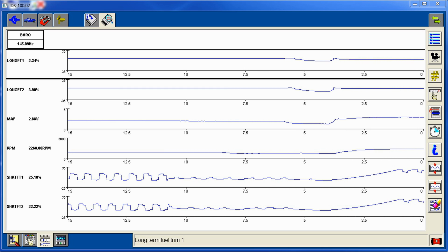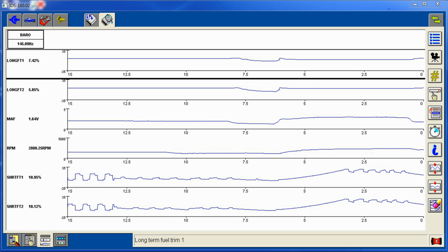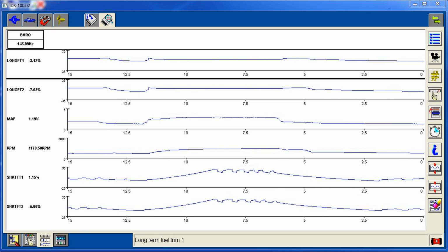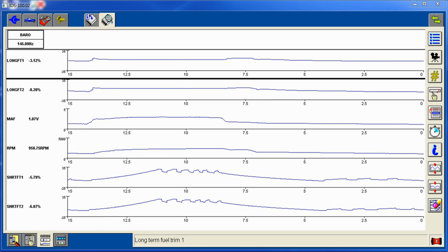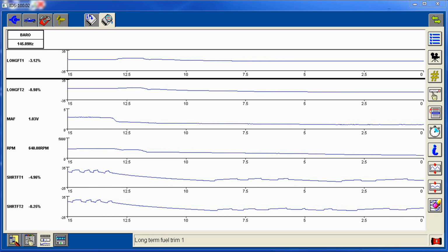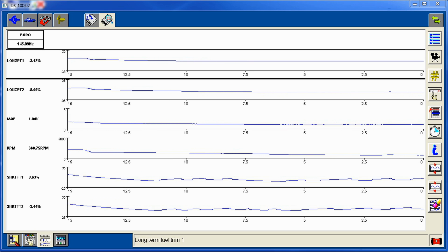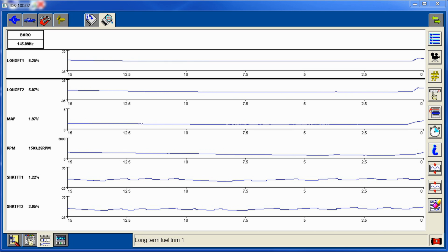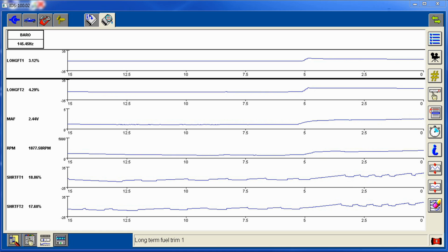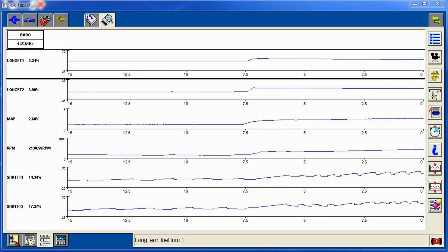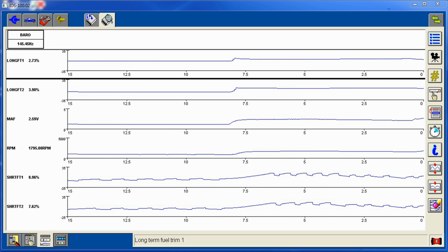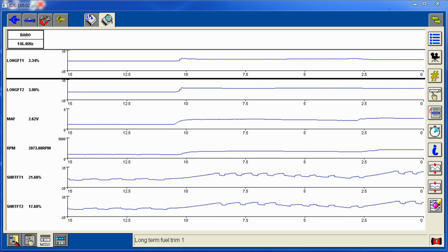Here we go. Look at the fuel trims, just skyrocket. Just underestimating what you're driving. It's not registering. So basically, when it's not registering, the actual airflow is coming in. More air is coming in than what it thinks, and therefore the O2 sensors react to that. They have the final say, and they are adjusting the fuel trims accordingly. So let's do a little bit of mid-throttle driving here. See the fuel trim? Whoa!